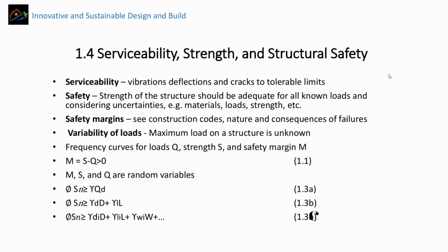And therefore we add a factor of safety for the strength, and we say the strength that we calculate for an element has quite some uncertainty regarding the type of material and the way it's built. So we use a coefficient lower than 1 in order to account for this uncertainty, and then we add a coefficient higher than 1 to increase the load on the building.